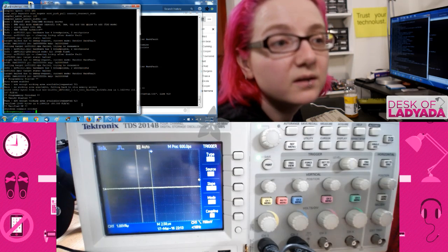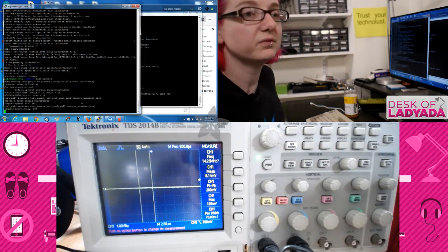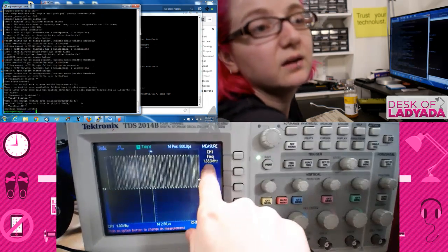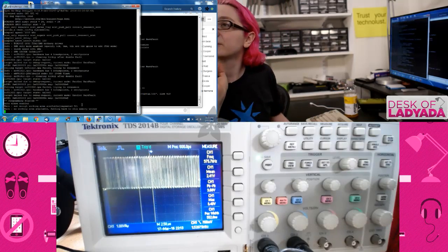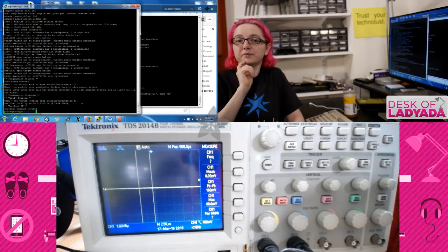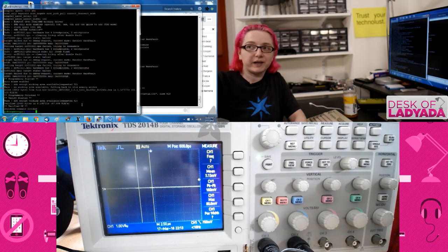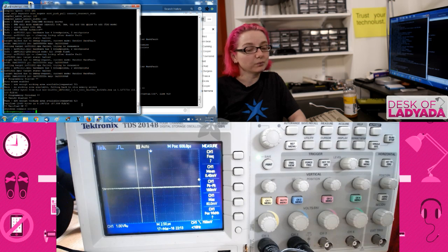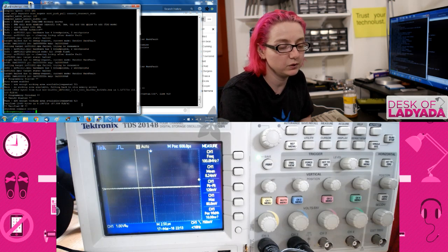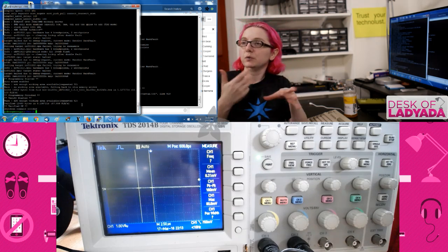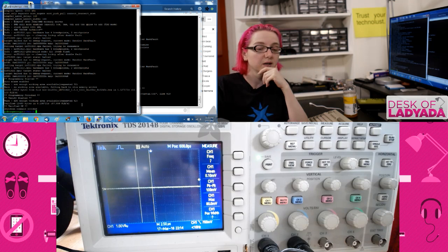And then, let's see if I can measure. I don't know if it's going to be able to measure the frequency fast enough. Looks like, yeah, about 1 megahertz. So incredibly fast. 1 megahertz, you're not going to get that from even a bootloader or native USB. That's going to be tough. And it just clocks the pins extremely quickly. Then after you're done, you have your programmed board, and then you can connect over USB and do whatever functional tests you have to do once the firmware is programmed in.